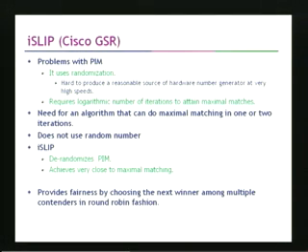The problem with this parallel iterative matching algorithm is that it uses randomization, both in the grant phase as well as in the accept phase, and it is hard to produce a reasonable hardware random number generator at the high speeds which it requires. Also, it requires a logarithmic number of iterations to attain the maximal match. Therefore, we need an algorithm that can do the maximal matching in either 1 or 2 iterations, and does not use random numbers.